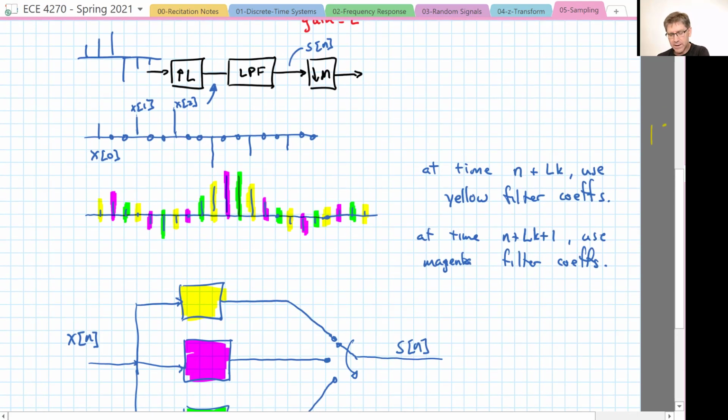After that, we throw away half the samples, or more. We throw away M minus 1 out of every Mth sample. So you could imagine there are some clever ways to maybe cause this to happen.